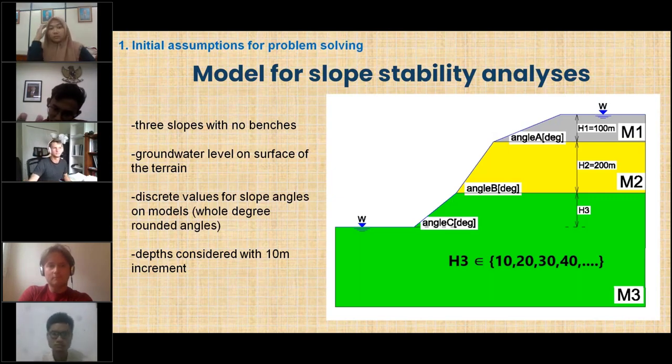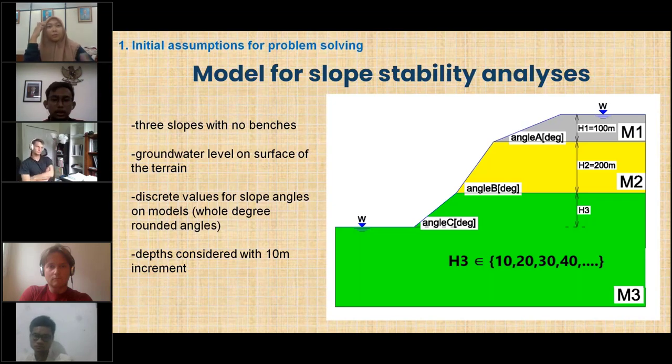Therefore, as well as for the reason that the max depth in the solution needs to be determined with 10 meters precision, the final solution profit was not exactly zero, but we searched for a solution that best meets the design conditions of the problem with the non-negative profit. Certainly, equalizing the profit of the final solution with zero is possible by slight modification of the geometry of the adapted model with positive profit. It could be done by a small increase of the amount of excavation, maintaining the stability of the model.